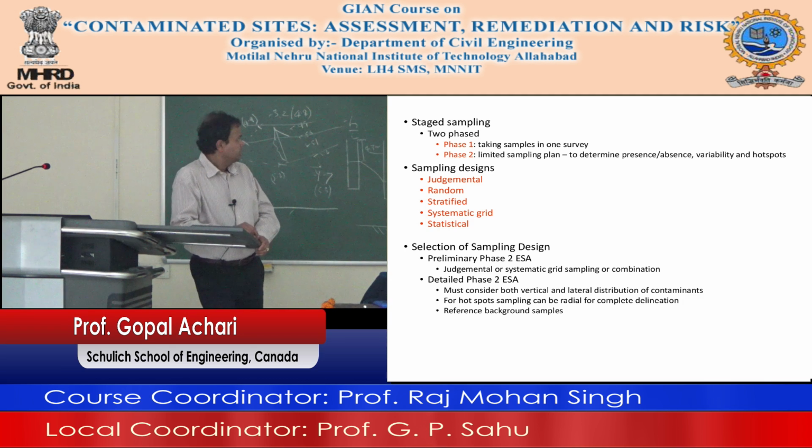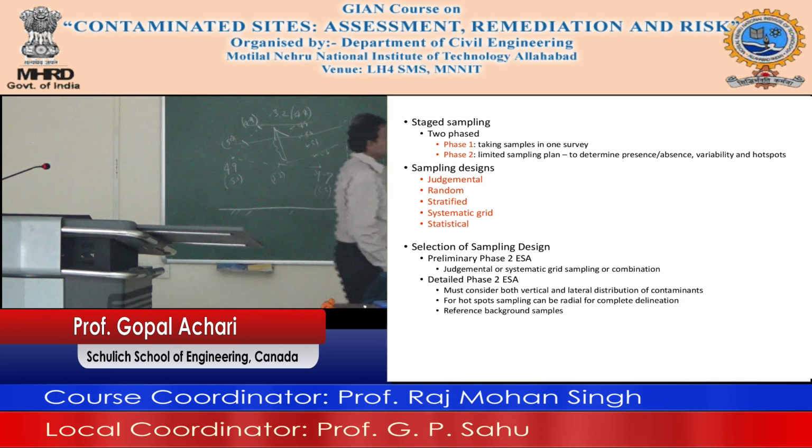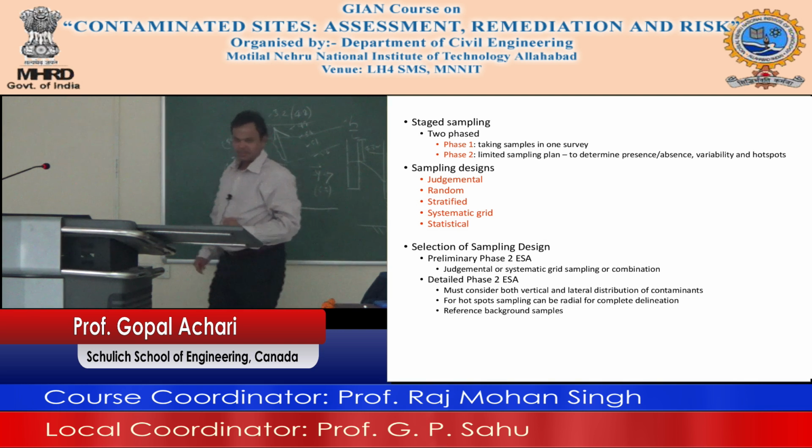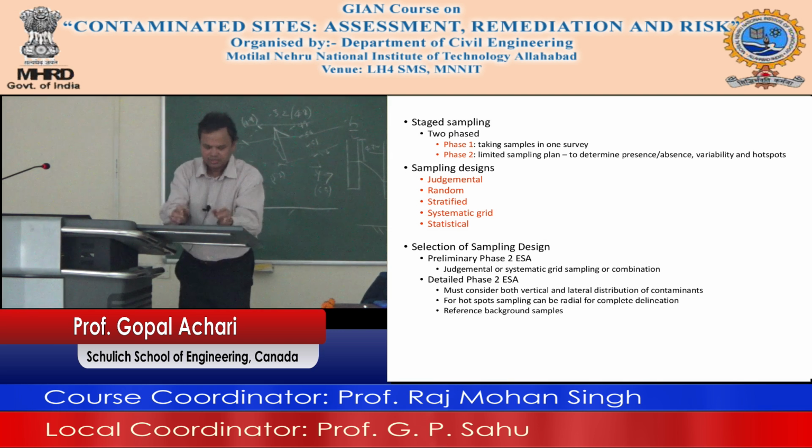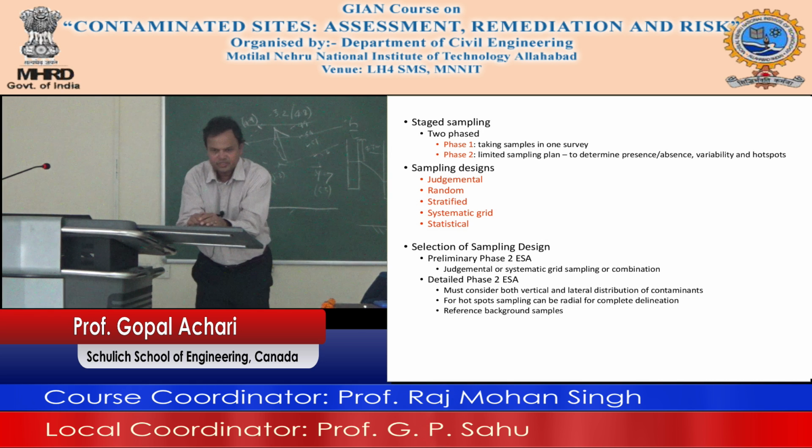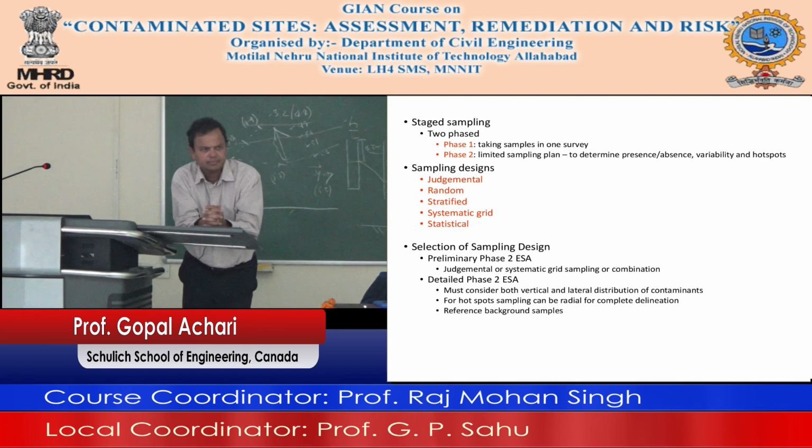Okay. You can also use stratified sampling. You divide the site into smaller areas, strata, and then sample from them. The other thing you can do is judgmental sampling. Judgmental means the phase 1 report says there is distressed vegetation there, so I'll do sampling there.